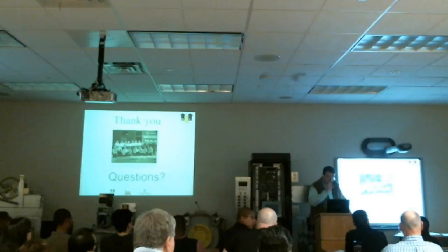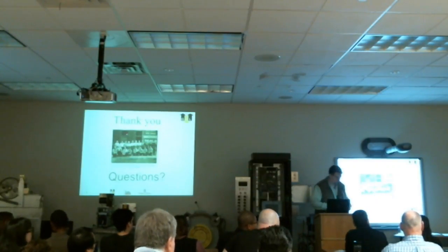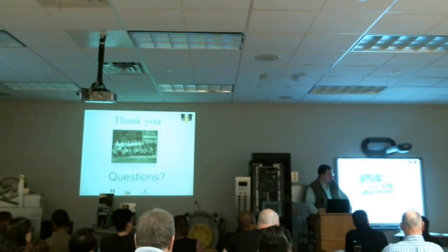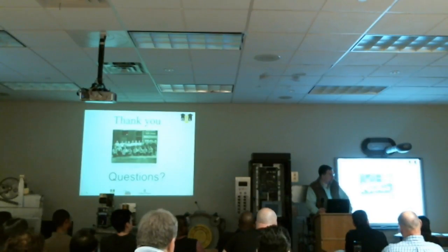As far as the DPM connection, some of the older door operators don't have the DPM. So will they have to also add this additional? We're going to be using a door close limit, the DCL. Every controller usually has a door open limit and a door close limit. As the DPM? Correct. Okay. So by code, you have to have the door close limit engaged in order to run.